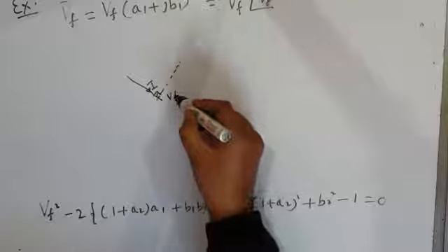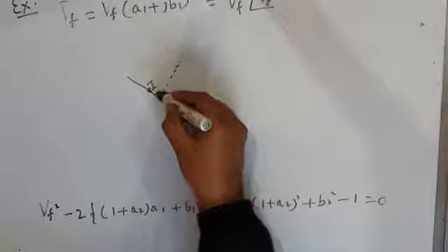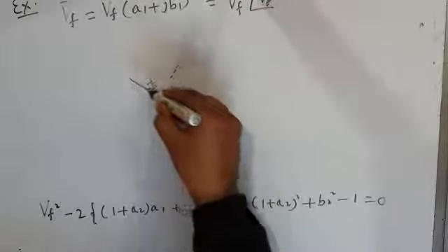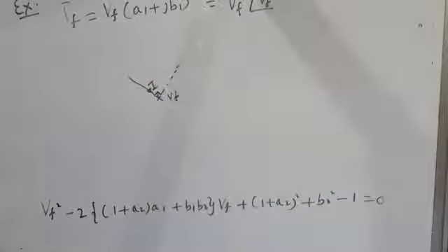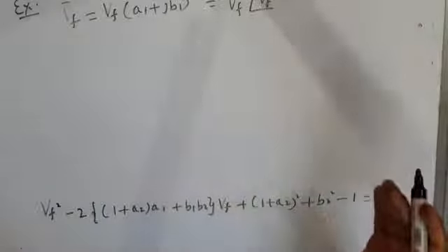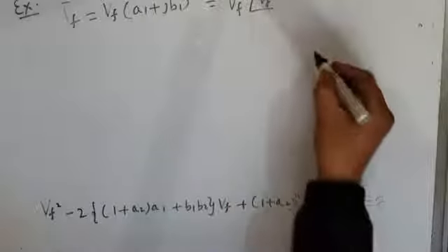Because what power does the DVR supply? VFI. And since the DVR injected voltage and current are at 90 degrees, it is supplying the reactive power only. And supplying reactive power means it does not need any energy storage or energy source at its DC bus.